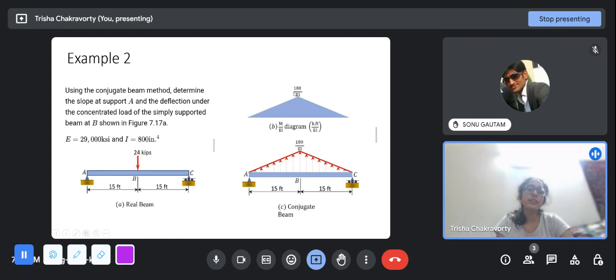By now, you should understand the nature of the bending moment diagram just by default, because if you have practiced, as it was covered in week one, I think it is obvious that the bending moment diagram will look like this. But of course, if you are not yet comfortable with drawing the bending moment diagram directly, you can use the basic way we had started: finding the support reactions, taking a section x from this end, finding the moment and then plotting it. It will look like this.